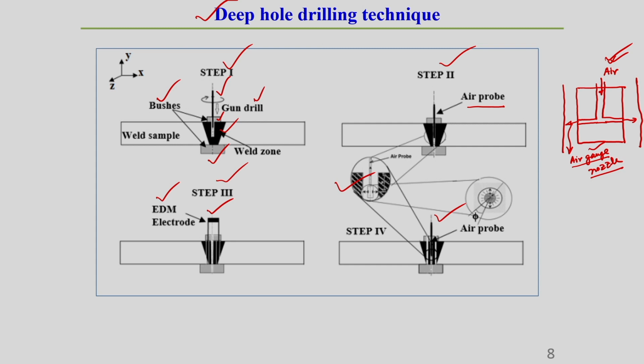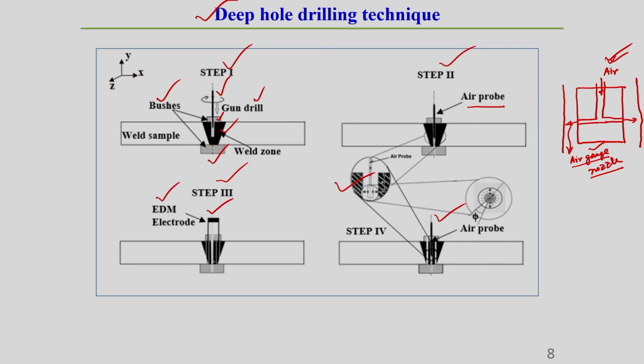Using this hollow cutting tool and EDM system, we can make this bore hole and remove the portion inside this welding zone.